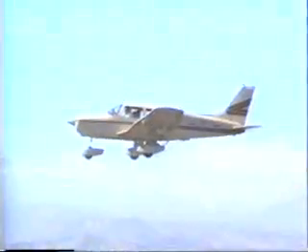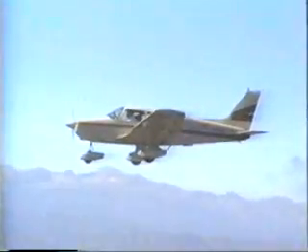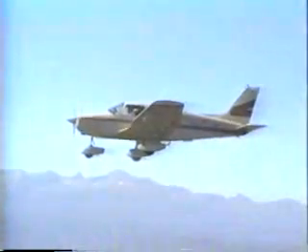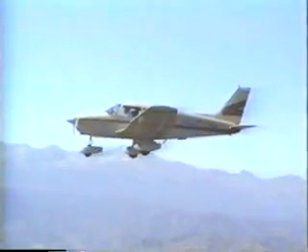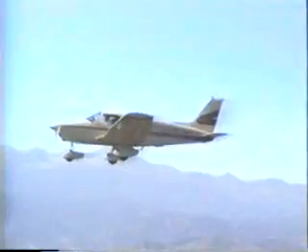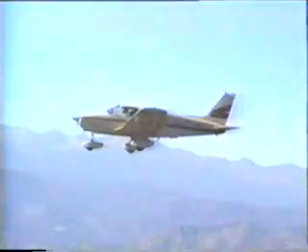Because the density of air decreases as you gain altitude, you must fly at a greater true airspeed at a given angle of attack to maintain altitude. Otherwise, the wings cannot generate enough lift. Likewise, the same holds true on hot and humid days.